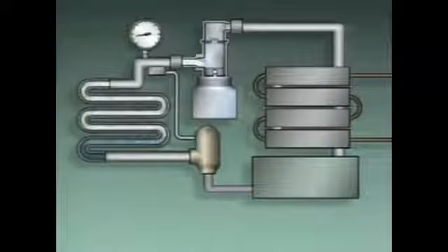When the compressor stops, the refrigerant begins to warm up and the pressure starts to rise, so the compressor quickly restarts. Then the pressure is reduced again and the compressor again shuts off. This on and off cycling, or short cycling, will continue as long as there is a low flow condition.